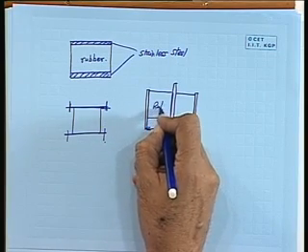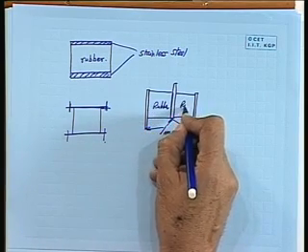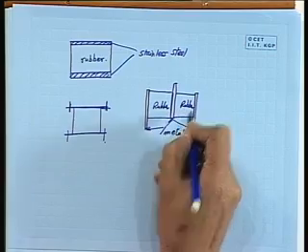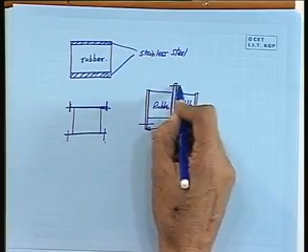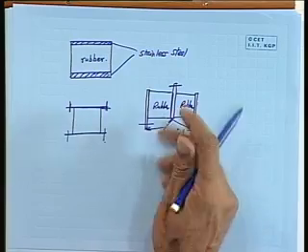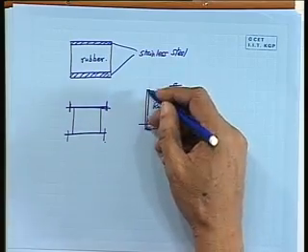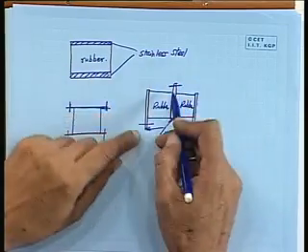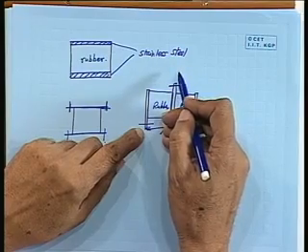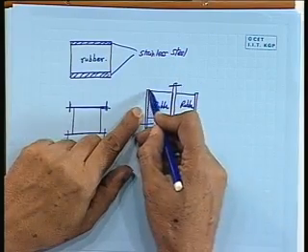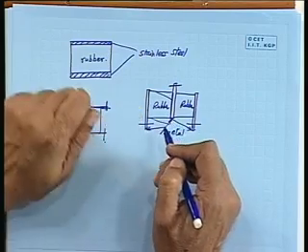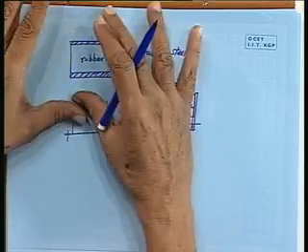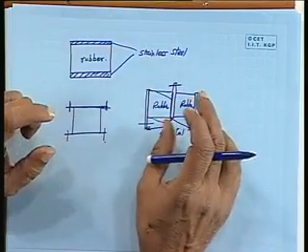This is rubber. You connect this to the foundation, connect this to the equipment, and when it vibrates, this will be in shear connection. This will go up and down when the thing vibrates. So, this will take a shape like this, which is under shear. This is a compression mode, this is a shear mode.